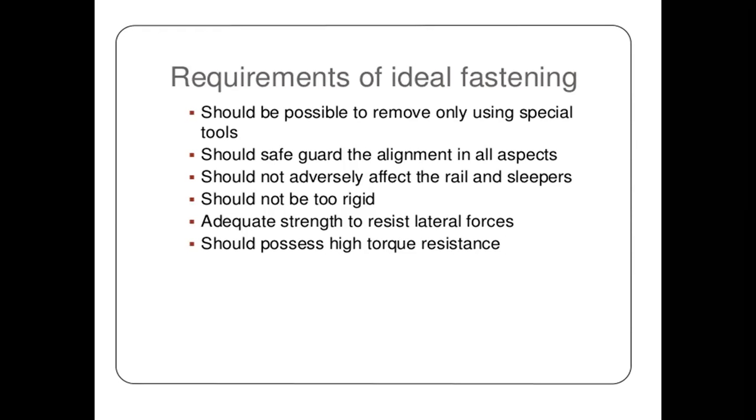If we fix the fastenings into the rail to safeguard it with the sleeper, these fastenings can also cause damage if the manufacturing of the fastenings is not of good quality. When RCC members or wooden sleepers are used and we fix these fastenings into the rail and sleeper, the sleepers may collapse, may be damaged, may split towards the ends, and can also be endangered.